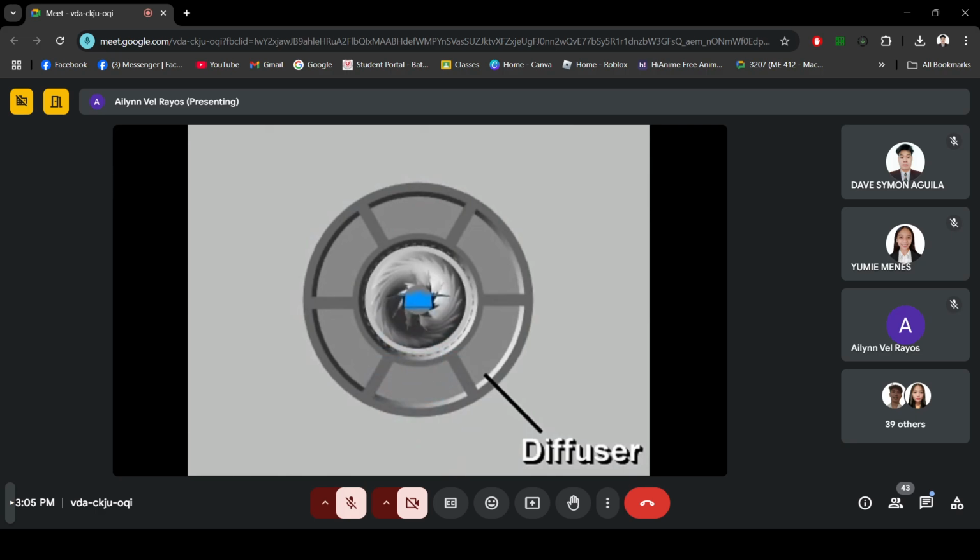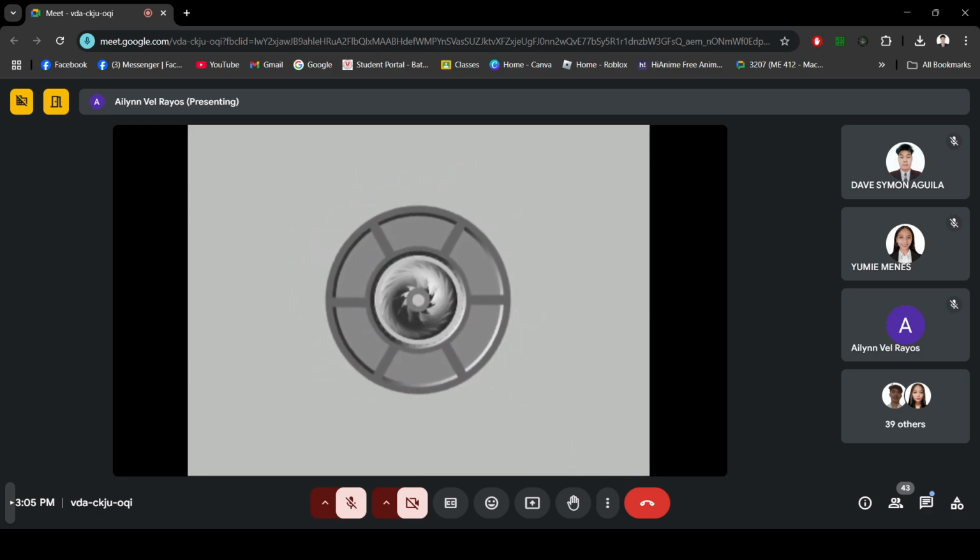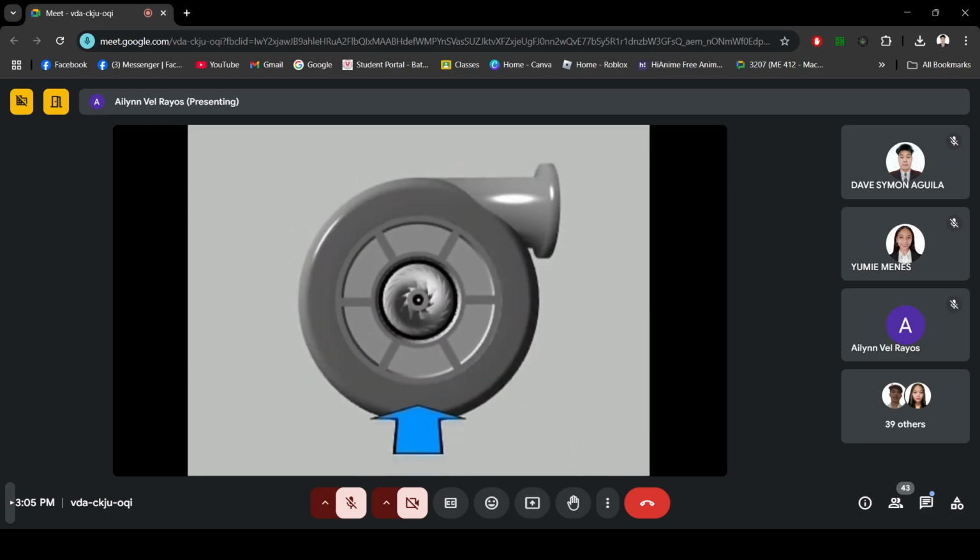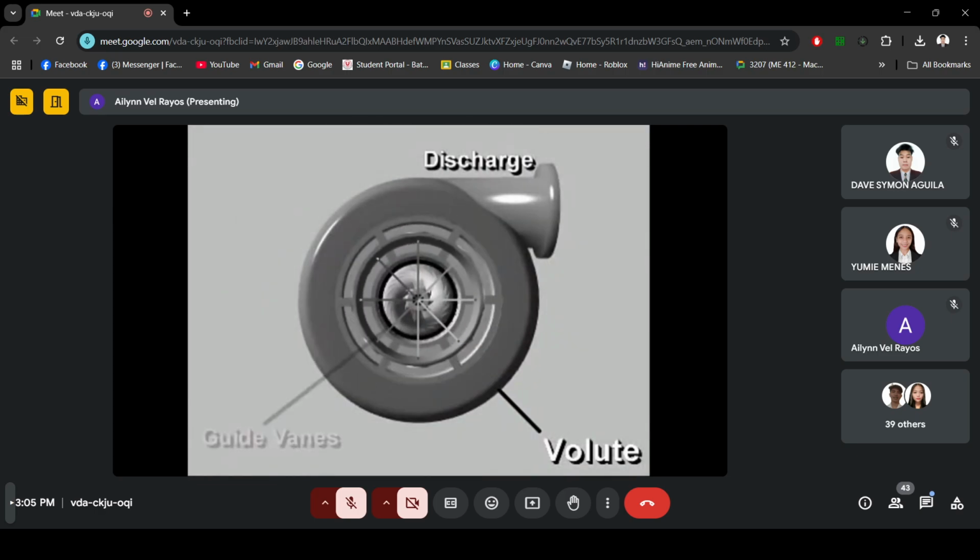As high-velocity vapor moves radially outward through the diffuser, the flow area increases, slowing the vapor and increasing the static pressure. Some centrifugal models have diffusers with vanes or pipes which change flow direction and further slow the vapor. The volute-shaped casing collects the slow-moving, high-pressure vapor from around the diffuser and conveys it to the discharge connection of the compressor. Inlet guide vanes control a centrifugal compressor's capacity.